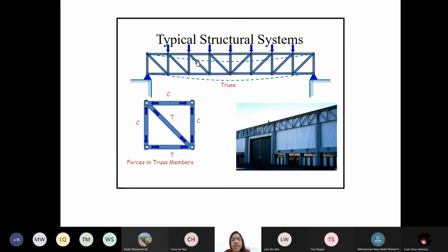See here, the profile is already given. You can also follow the profile. Because of the profile, this is compressed, this is tensed. This is compressed and this is tensed. This is a very basic thing. You don't have to worry about much now, but understand where the compression is by imagining how the member will behave. Where is the compression? Where is the tension? That's the point.